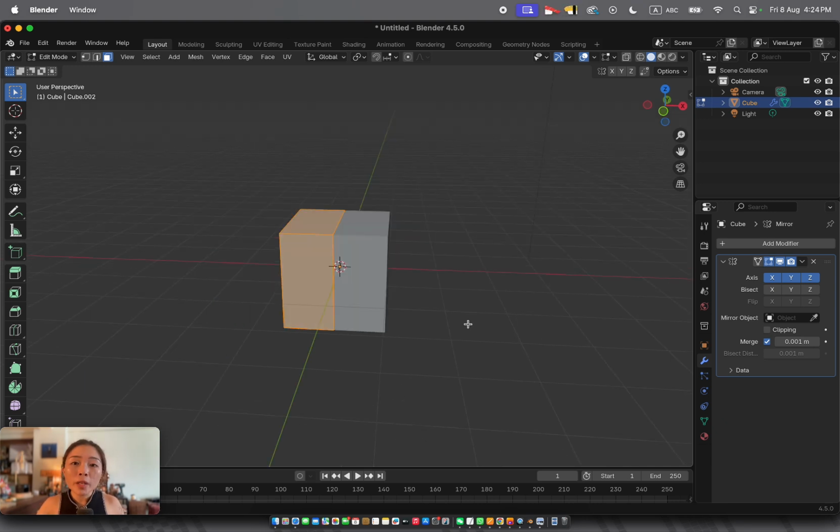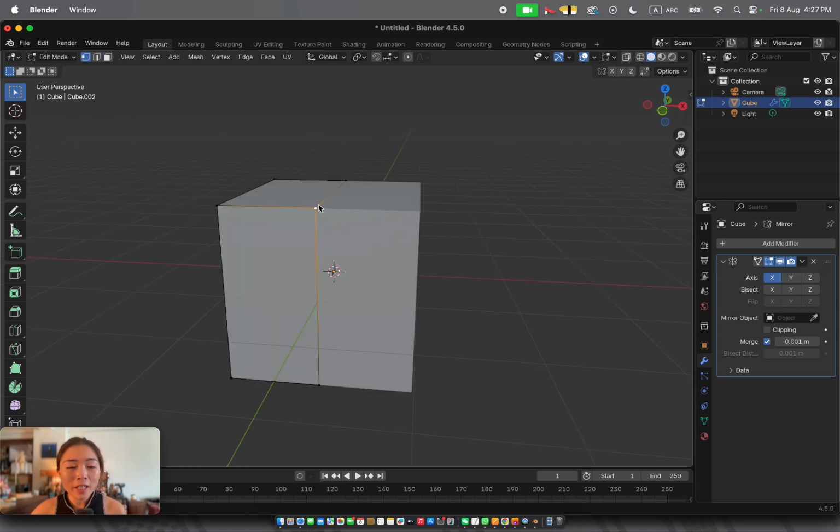When do we use the mirror modifier? You can take the example of the bathroom sink, where I create half of it and then put it side by side with the other half using the mirror modifier, and then I use the spiral array to clone the other 7 parts, right? In this case, I would just have to do the modeling on this side and then turn on the mirror modifier. Sometimes, if you are very new to the modeling technique, you will make a mistake like this.